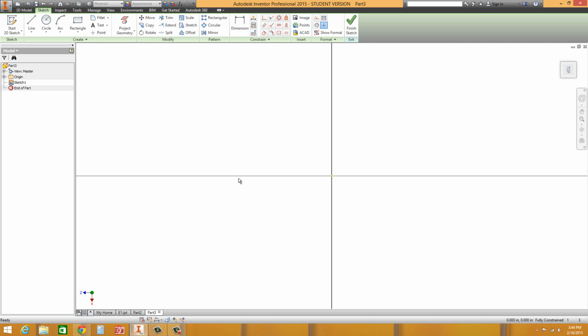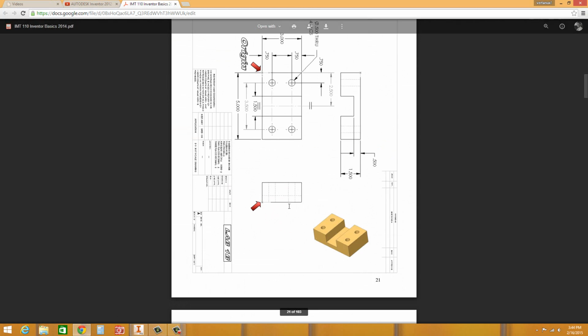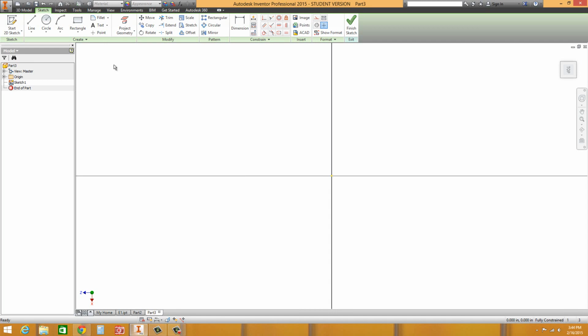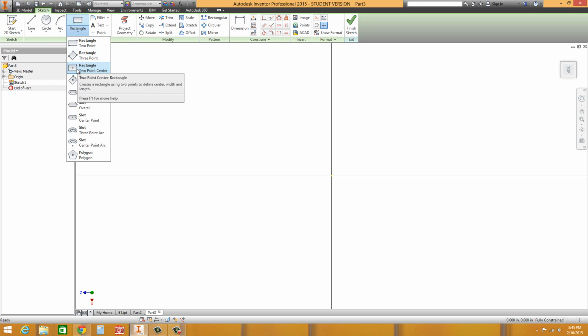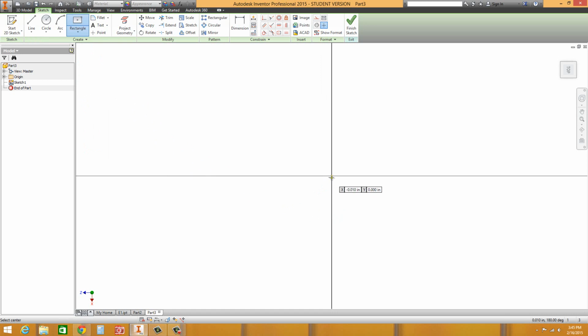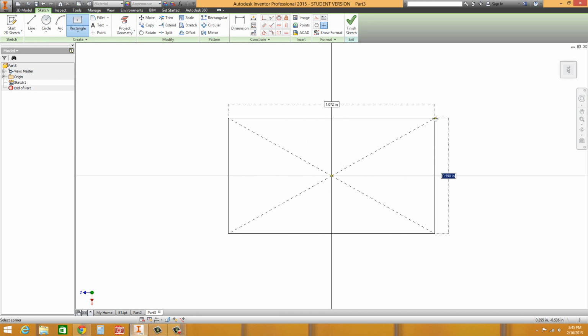Also, the model is symmetric, even though in the print that I provide, which is a terrible print, I apologize for it, you'll see I have an origin base. When I first wrote this lesson years ago, I used to like to have it locked into the origin, then you would learn how to center things. But in this case, there's a tool which really comes in handy here under rectangle, and it's the 2-point center rectangle, which I'd like you to give it a try right now. Click on 2-point center. Click on that center point first, which is the center of the crosshairs, and drag it out.